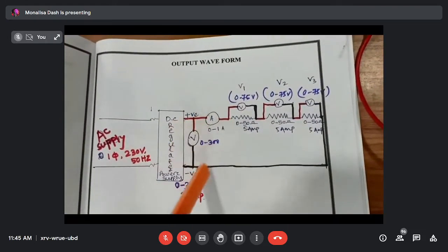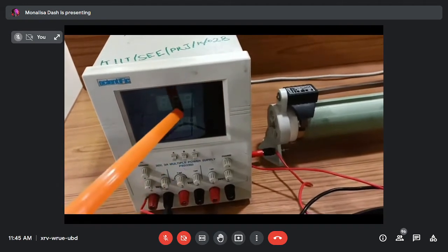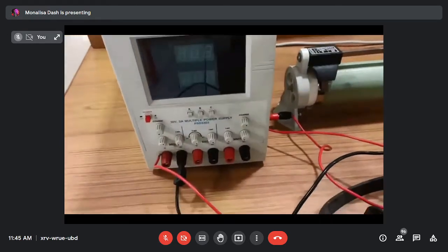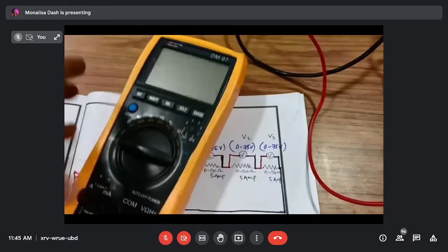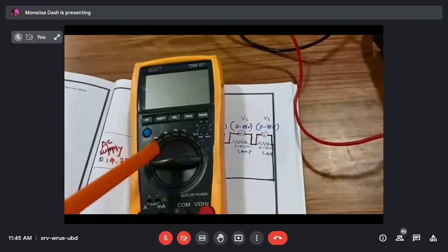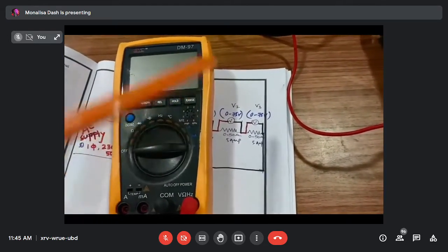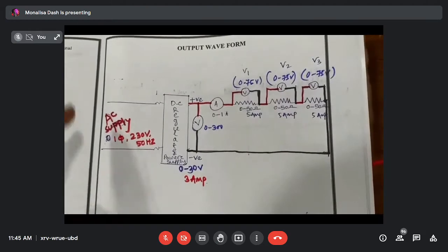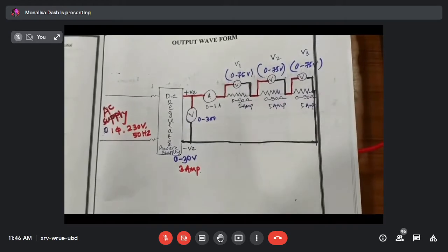For that voltmeter, one display meter is there, a digital meter. From there we can also measure the voltage reading of the supply voltage, or by one multimeter, we can also measure the DC voltage across these 2 points. Now our circuit connection is over. Now we will switch on the supply.